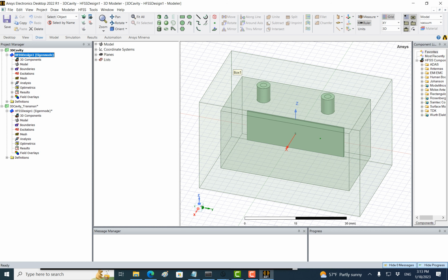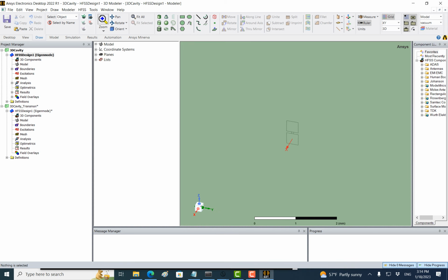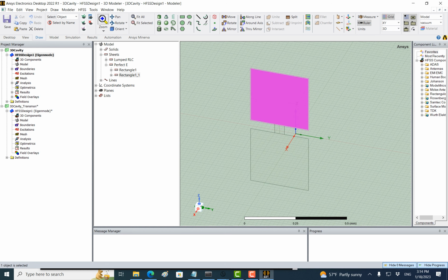Usually people might then fabricate their Josephson junction, like here. This is the transmon, as I mentioned in another video. This is mostly just for the capacitor because it's a Josephson junction, so you have a huge capacitor. And then this part is to represent the transmon itself, including the Josephson junction itself, the pad, and also the aluminum oxide dielectric, right? Because a Josephson junction is superconductor, insulator, superconductor.